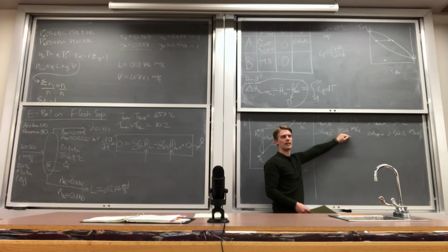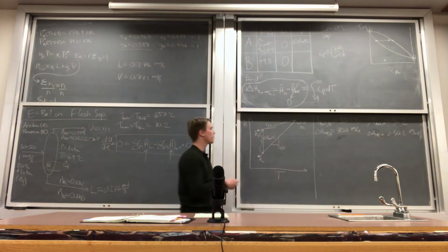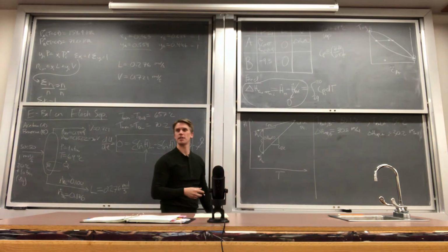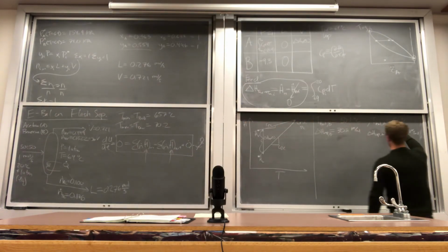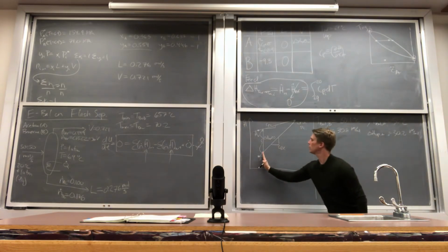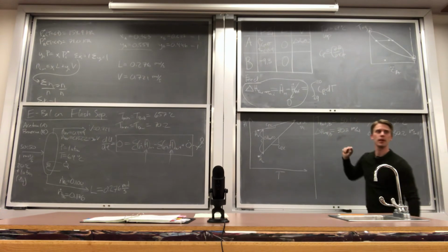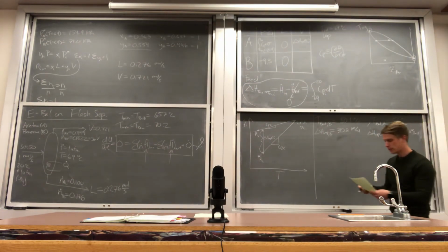It's going to be higher because we're pulling it further away from its critical point. The heat of vaporization only increases as you lower the temperature. In the case of acetone, its normal boiling point is right here. We're estimating it at a higher temperature, which means the difference between liquid and vapor gets smaller. So it's another way to do a double check for consistency.